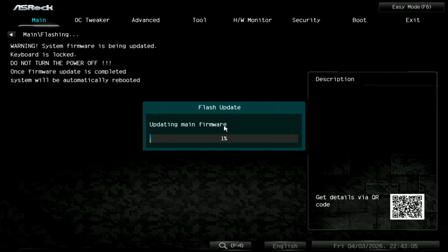It's generally really important that you guys look at updating a BIOS, especially if your board has been on first release. First release BIOSes, especially on AMD, are incredibly buggy and can cause stability issues. So ideally, my recommendation is when you get the system up and running, update to the latest non-beta version and then just do your settings and call it a day.